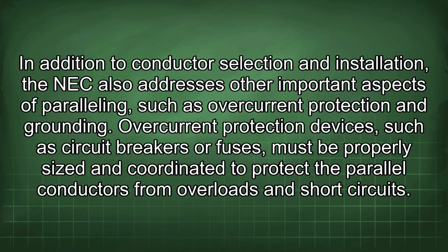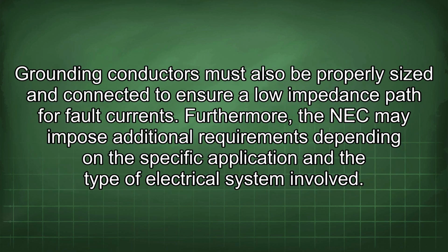In addition to conductor selection and installation, the NEC also addresses other important aspects of paralleling, such as overcurrent protection and grounding. Overcurrent protection devices, such as circuit breakers or fuses, must be properly sized and coordinated to protect the parallel conductors from overloads and short circuits. Grounding conductors must also be properly sized and connected to ensure a low impedance path for fault currents.